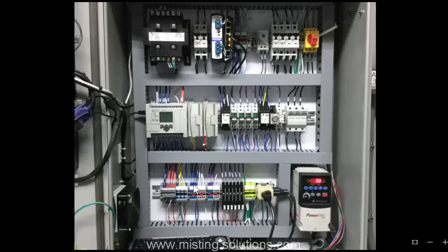And these 24-volt DC wires actually go to the bottom, which is the output of the Allen Bradley controller. You can't see that they're blue down here, but they are. They go into this controller, which has dry contacts in it, and these are the signals for a variety of components. Mainly the 24-volt DC signal that drives these relays on and off for the solenoid valves.